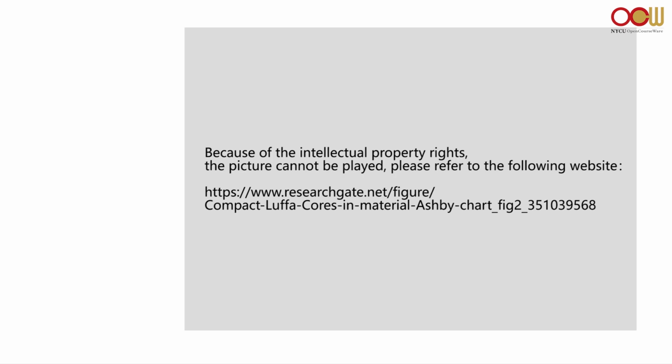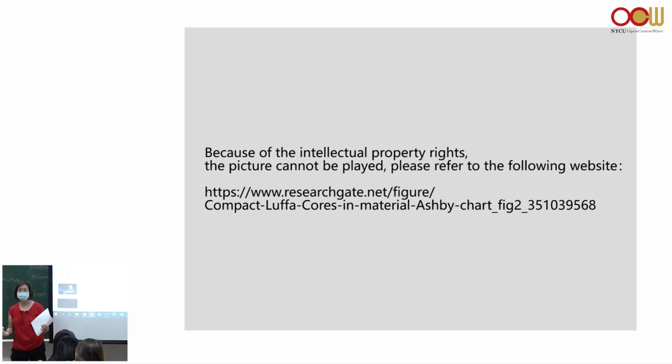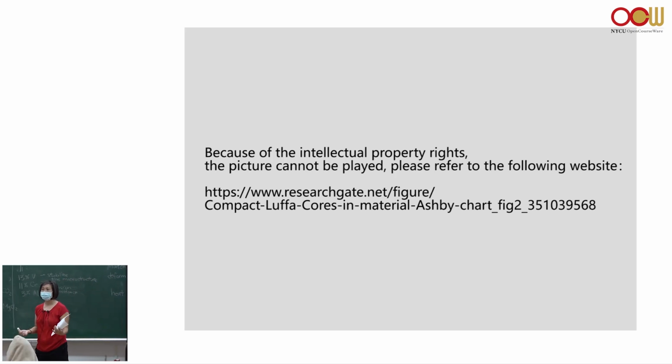Aluminum is here. Okay, so they're both very high strength to weight ratios compared to something like copper or tungsten or lead, zinc. Okay, so you would look at a diagram like this depending on what kind of material properties you want, and you could select your materials that you might want to try out.